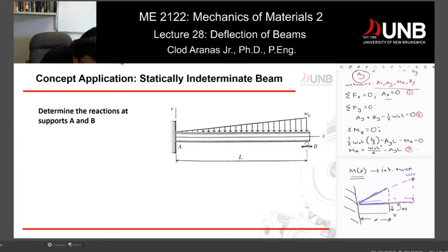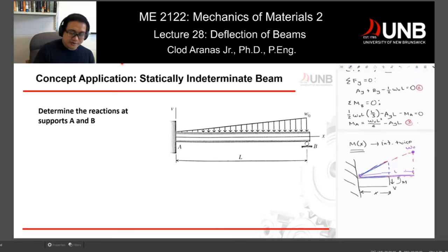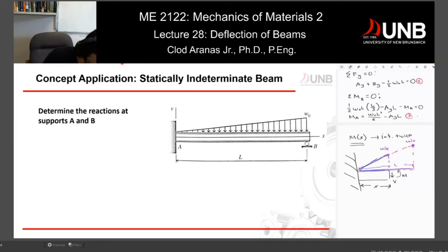Okay. So this would be L. Now, remember in the exam, I mentioned bigger triangle and smaller triangle. What do I mean by that in the exam? So if I can call this one as W_x, because that's after slicing at length x, I can say that W naught over L is equal to W_x over x. So in terms of triangle, that makes sense because it's just the ratio between this length right here and this length here. Same thing for this smaller triangle.